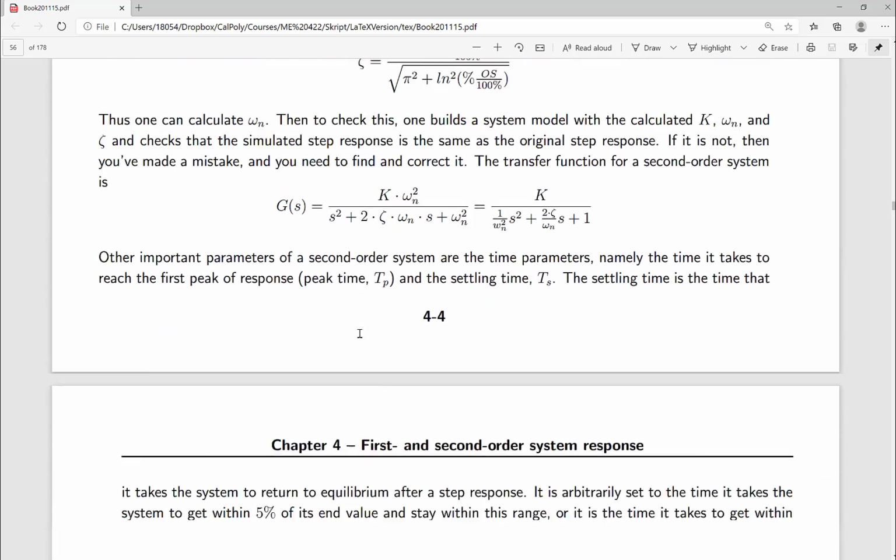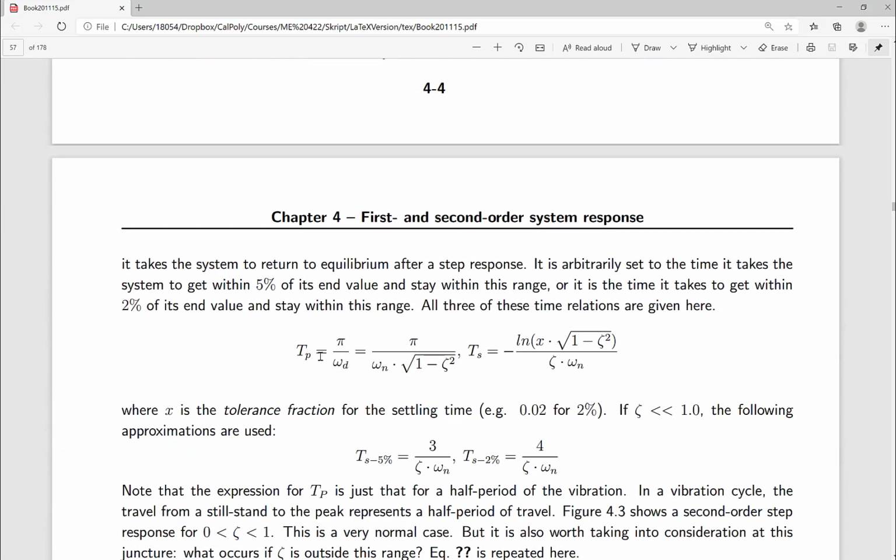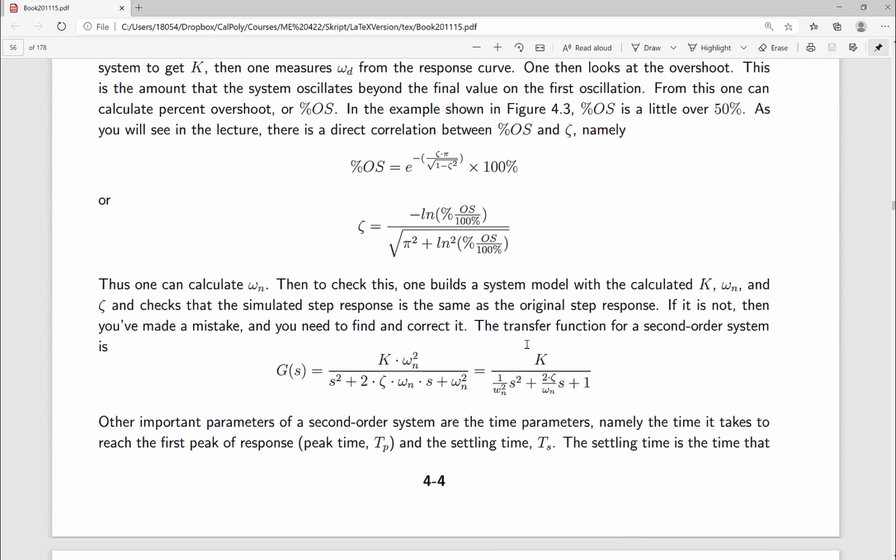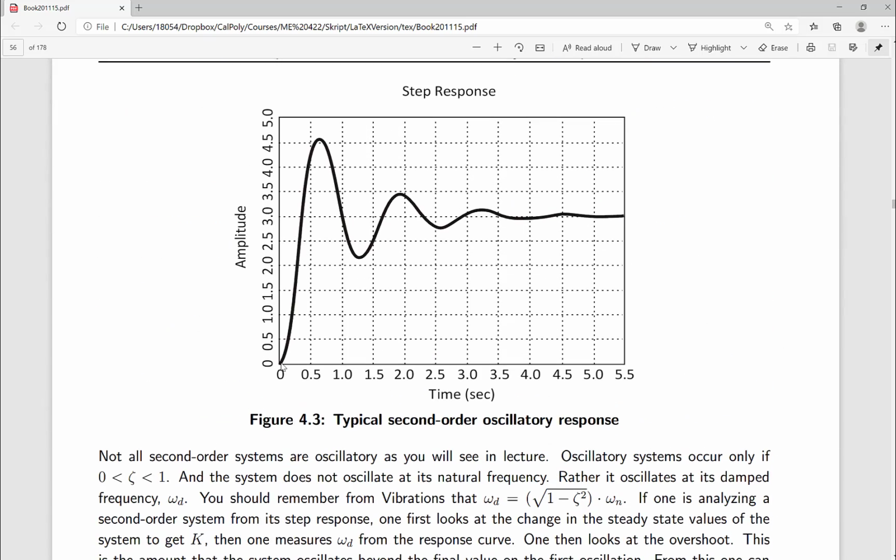So that's an interesting parameter for a system and really tells how fast it's going to respond. There's another parameter called the settling time. And the settling time, of course, these are just given formulae, although I described where this one comes from. The settling time itself is how long it takes to get from the beginning to the end.